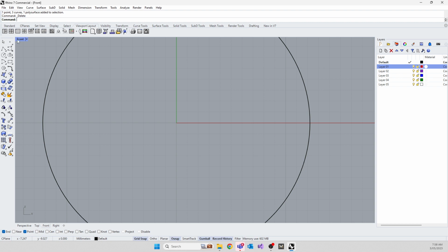We're going to go to the command line. This time we do want a polyline, which just means one line following another line following another line. So we're going to grab that one, and you'll see that my mouse is now snapping to the grid in the background. So when I draw something that's exactly 3 by 3, that's much easier now. And if I want exactly one little gap between them, that's fine. So that's what a grid snap does. Very handy when you're drawing stuff that has precision that's measured by units.